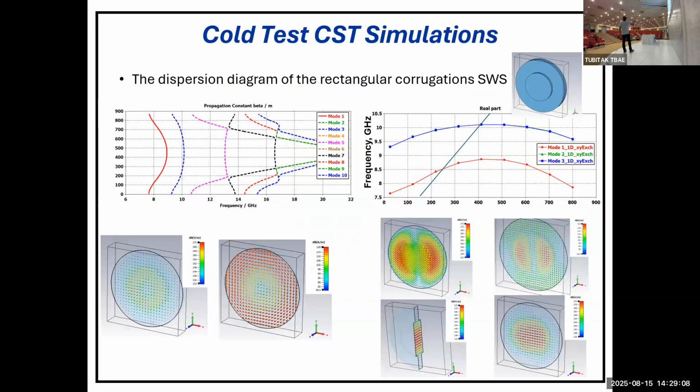Again, CST is very powerful if you just have an ideal case where you have one period, and you tell CST that this is a periodic boundary condition, meaning repeat this to infinity from both sides. It's going to give you a smooth line, what you see here. This is one unit cell with a periodic boundary condition. So basically, CST will consider going to infinity. Yes, you have to choose the boundary conditions.